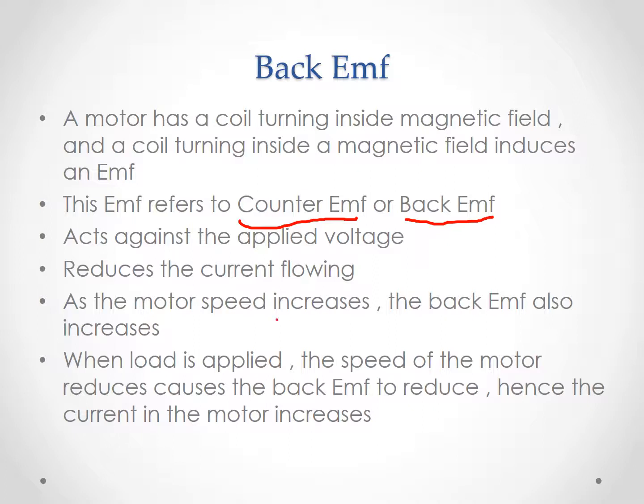As the motor speed increases, the voltage increases, the current increases, therefore the rate of change of flux increases. Lastly, when a load is applied, the speed of the motor decreases, which causes the back EMF to reduce, hence the current in the motor increases.